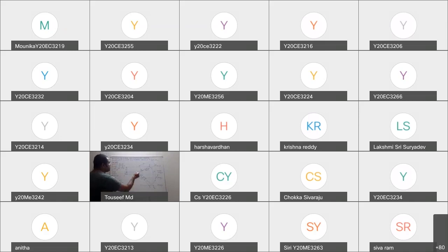Once I know my points HT and VT, if I simply extend ABV to some extent and draw the vertical projector from here, it becomes HT. So from that we can say that A, B, V, HT lie on the same line. A dash, B dash, H, VT lie on the same line. Okay, students, is it clear?